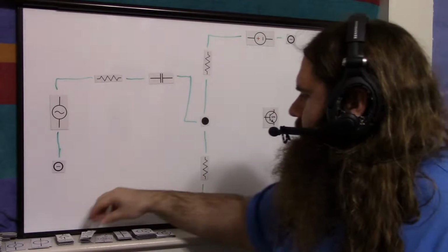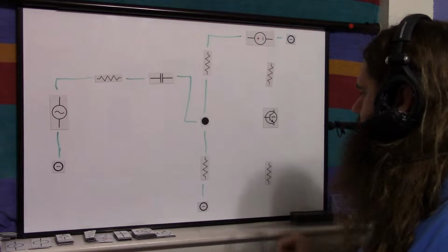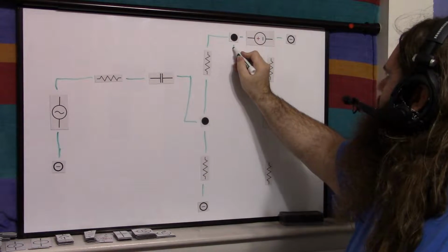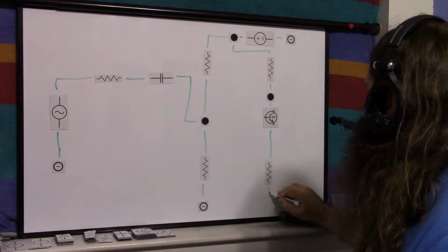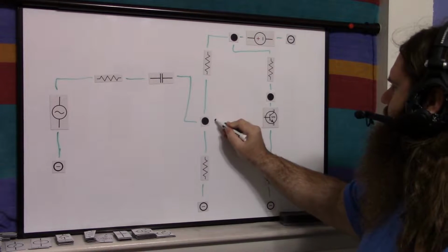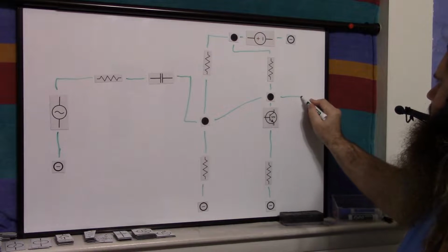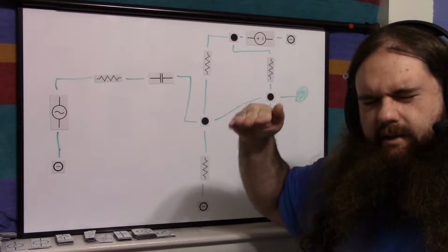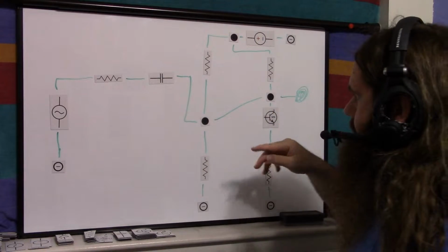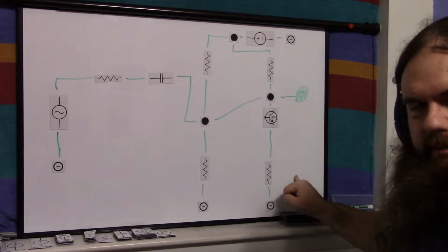We have our transistor with the collector and emitter resistors, and the same power feeds this one, goes through the transistor and out to the reference voltage. The signal connects there, and this is the signal output. So the bias sets the base, essentially the voltage of the base at a midpoint. So the bias interacts with the emitter resistor.